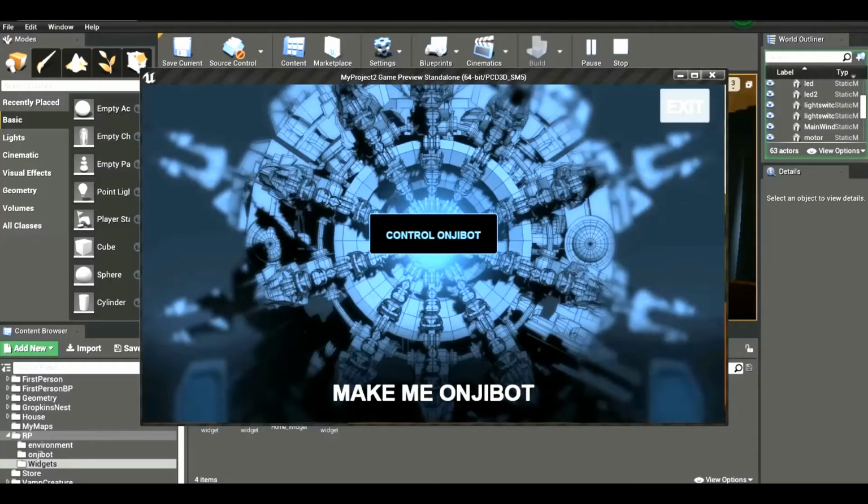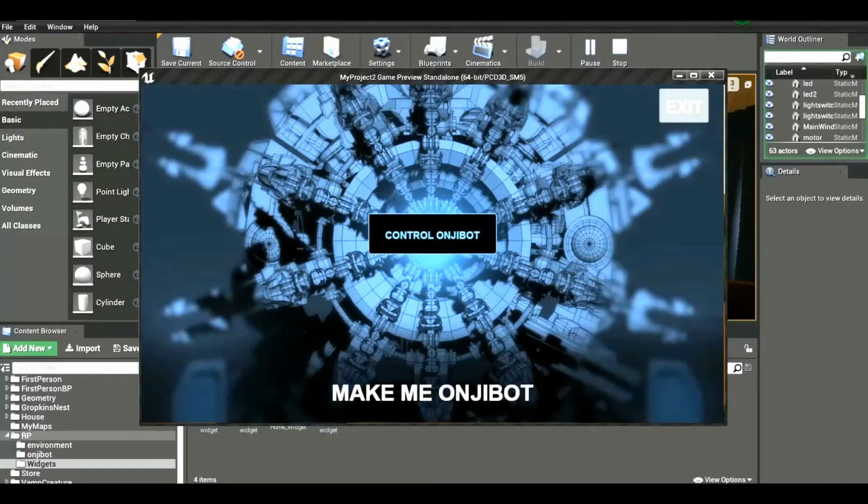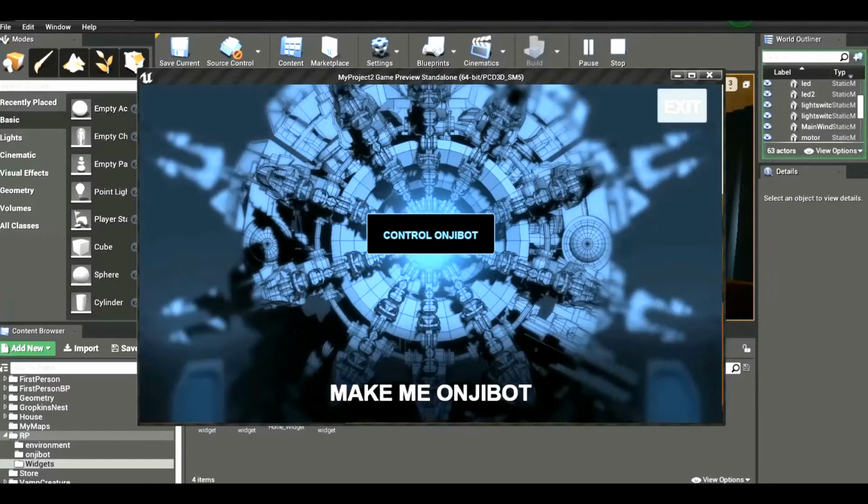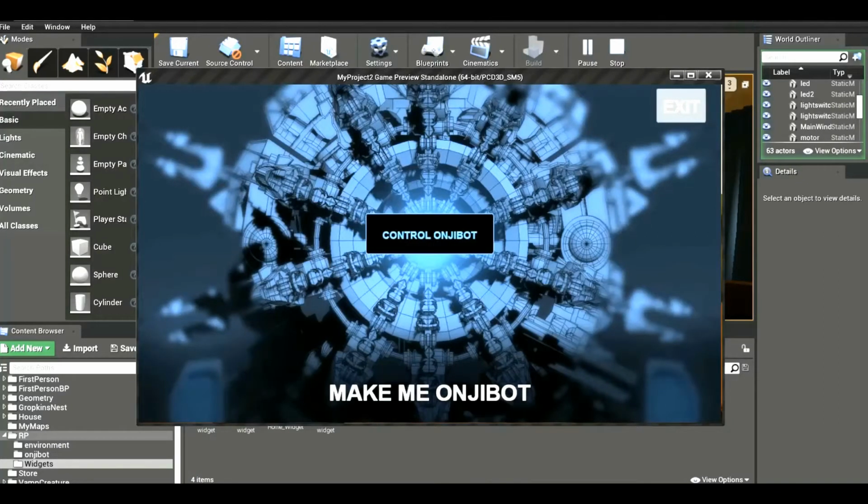In these videos, I want to show you that you can control your own robot using Raspberry Pi. But first, we're going to test communicating to the Raspberry Pi using UE4. I am communicating to Raspberry Pi online by using UE4 to load PHP files from my hosting. Those PHP files have code that writes commands into a text file that's also in my hosting. And then Raspberry Pi is constantly reading those text files, or that one text file that has the command.